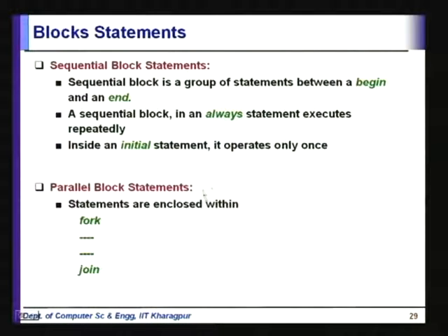You can also have parallel block statements, which can be described by enclosing them within a fork and join. Whatever statements are there between fork and join, you can think of them as executing in parallel. This is in behavioral Verilog.